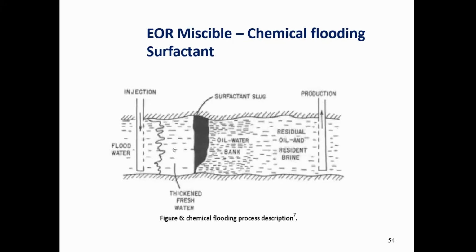The answer: I will inject soapy water, and that soapy water will dissolve the oil and give me less adhesivity, good mobility and reduced viscosity. And then because of the pressure of water injection, the oil will move with the soap together to the producing well. And in the separator, I will separate the soap from the crude oil.